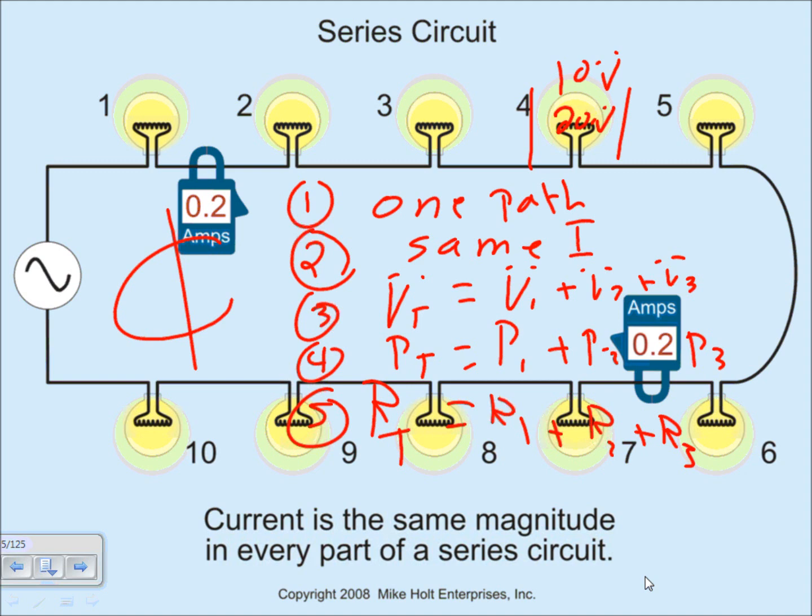The most important thing is fluctuation. The voltage fluctuates. That's not how we make equipment. We make equipment with constant voltage, and the current fluctuates. When I say fluctuates, I mean double, triple, half, a third. Within 5 to 10% fluctuation of voltage, that's an acceptable range. But I can't double, triple or quadruple the voltage like it does in the series circuit. So can you see the disadvantage of this circuit is this right here.